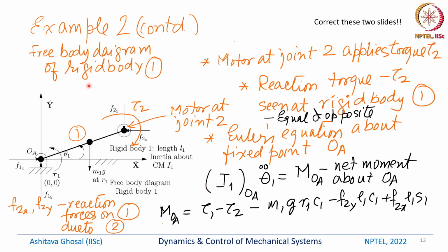So let's continue. In the Newton-Euler formulation, or when we are trying to use Newton's law and Euler's equation, we have to draw what is called a free body diagram. And what is a free body diagram? We just take a look at each link at a time. So this is link 1. When you draw the free body diagram, you are basically breaking the link or removing this joint. If you look at this joint, there will be some reaction forces from the ground.